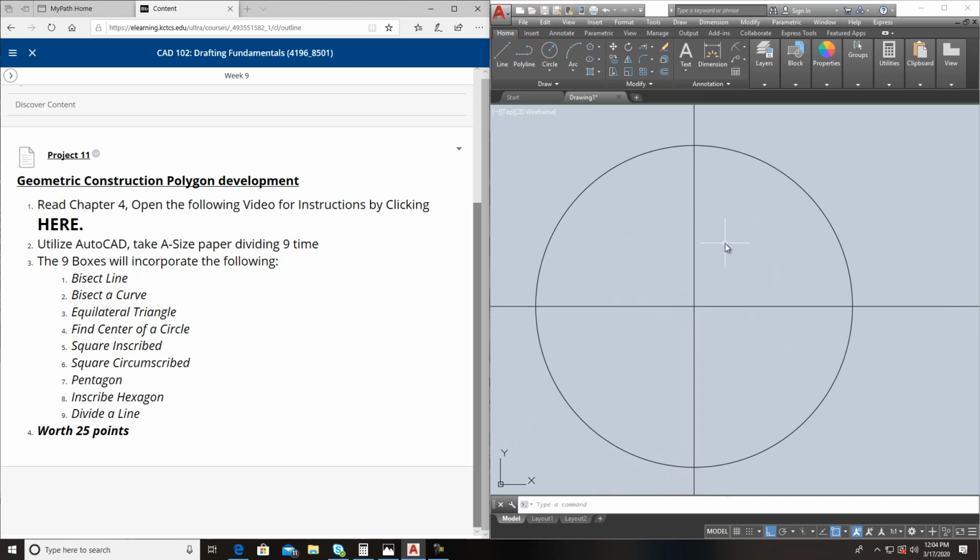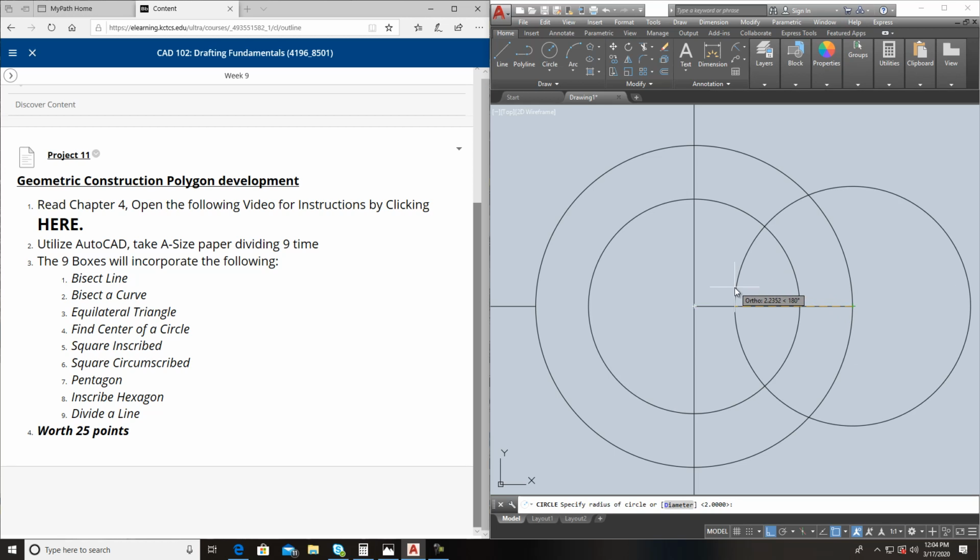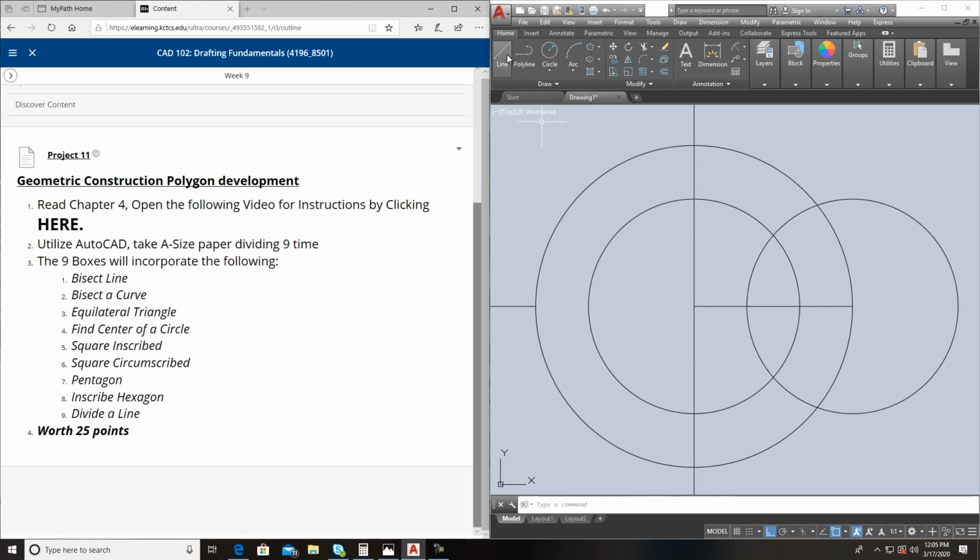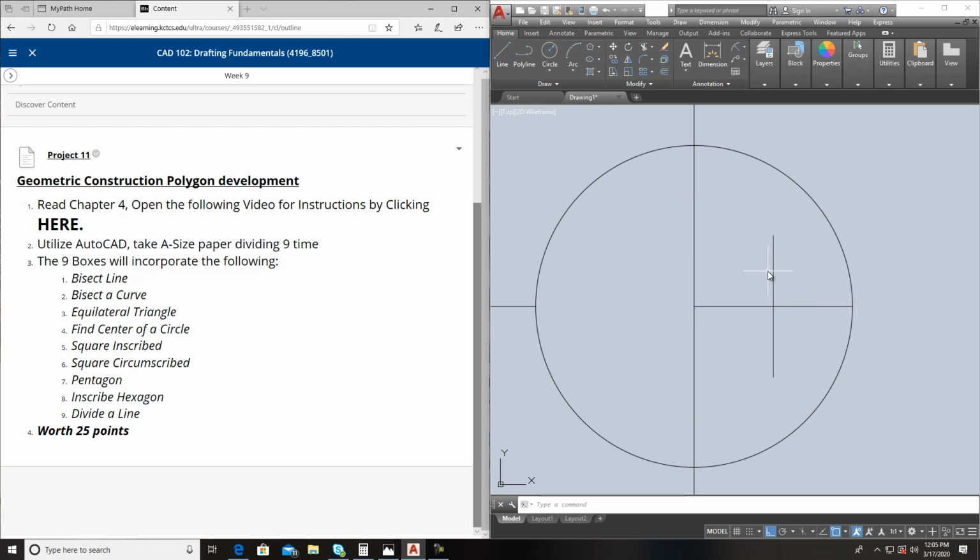First, you're going to take and you're going to bisect this little bit of line right here. Let's get in there and do that real quick. So I want to trim that off and trim that off for the time being. I just want to bisect this line, and you guys remember how to do it. You come here, stick your compass in there, come about halfway, say 2, and come over here and 2, and that's where you're going to find your midpoint of that line. Okay? So that's the midpoint of that line. I'll go ahead and delete those out.